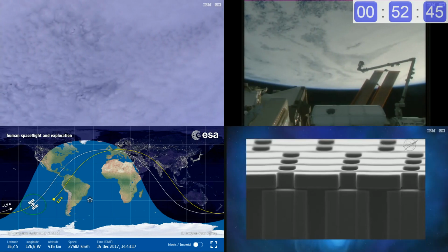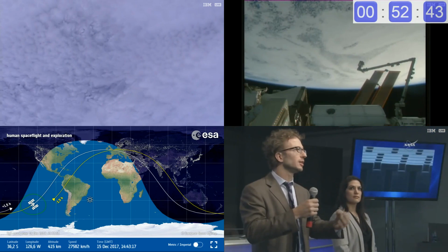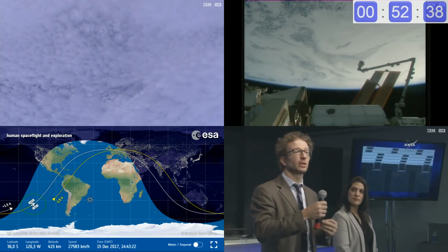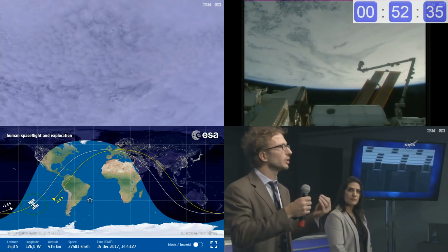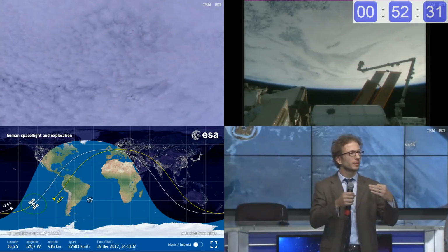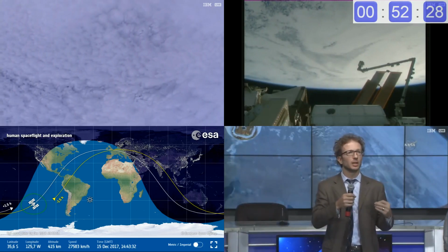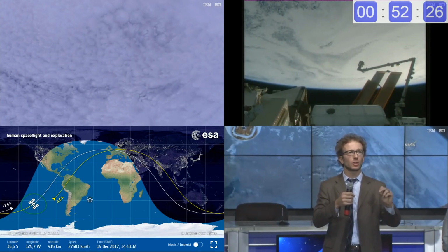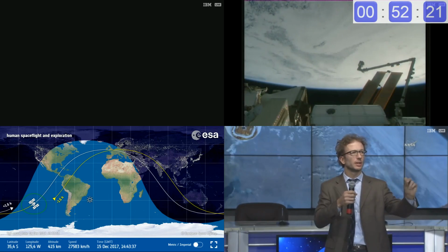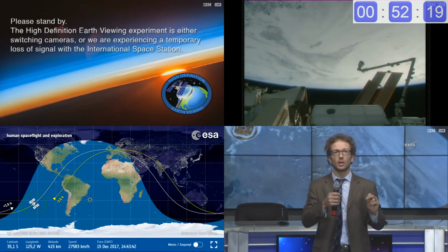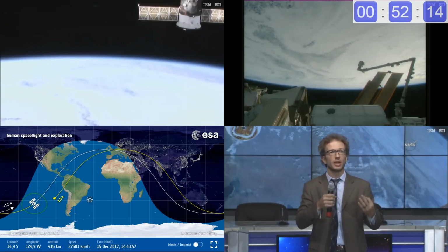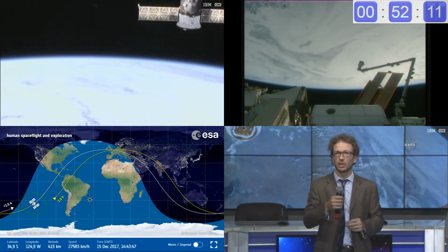So very, very tiny. Why do we need to go to that extreme in manufacturing complexity to use this type of technology? Well, the reason is because we have realized that if we take channels that are that small and we use them as a rate limiting membrane, we can achieve a very steady and controlled delivery of the drug outside of an implanted reservoir for a period of time ranging all the way to months and years, without any sort of pumping mechanism on board of our implants. So that makes a very small, very effective implantable delivery system.